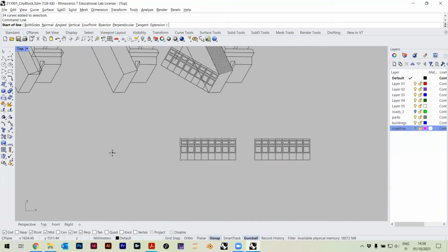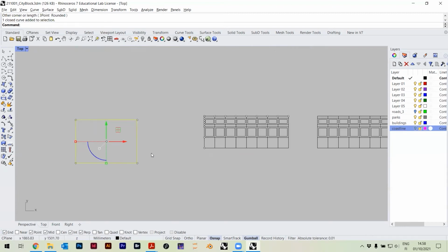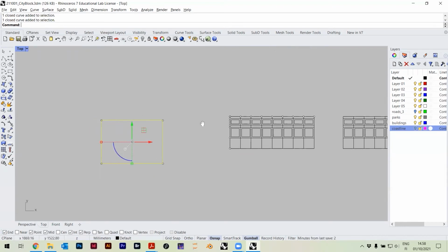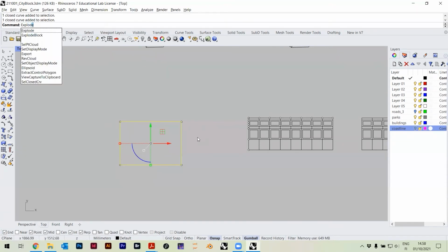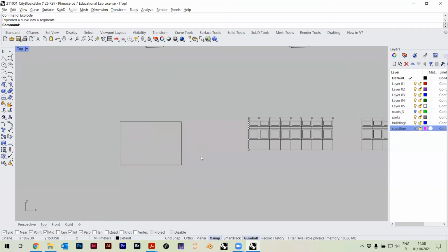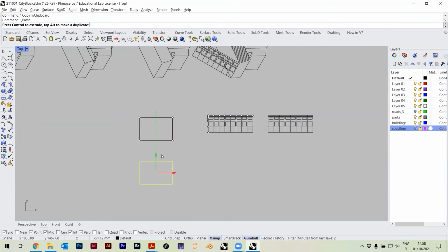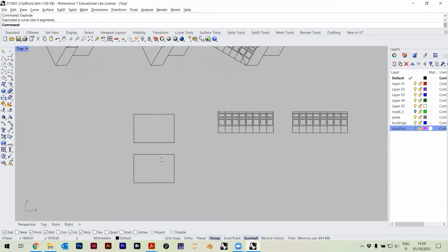These are kind of subtle, but if I have a rectangle, now this is not a group. This is actually a polyline, which I can explode. So I can destroy the polyline into its component parts. Actually, let's go back. So now I have a closed curve. It's a polyline. I can paste it, put it here. I can explode it. Okay. So when I explode it, I get individual lines, and then now I can group them. I just write group.